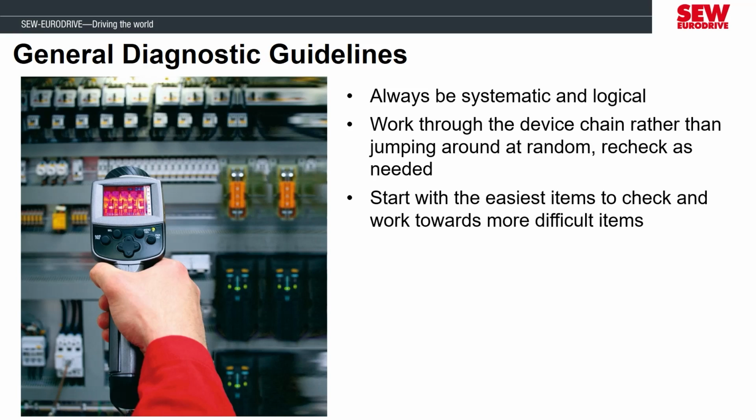These could be things like checking the fault history, taking measurements with a multimeter, looking for bad electrical connections, etc. If you start diagnostics with time-consuming tasks like removing and replacing components, you may be wasting efforts on items that aren't the root cause. It's also possible to cause damage to new components by installing them into a problem situation before knowing the root cause. Also, it's good practice to recheck items again or have someone go behind you to check as well, since it's easy to make a mistake or overlook something in your diagnostic process.